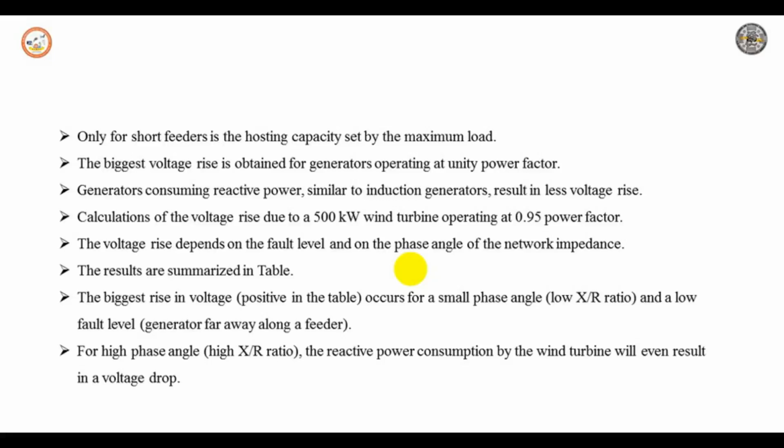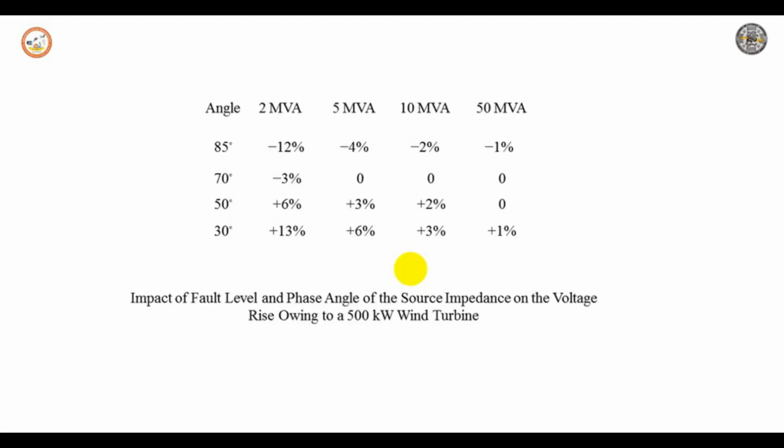The hosting capacity here is strongly dependent on the method used to prevent undervoltage. Using off-load tap changers for the distribution transformer will give a high voltage magnitude during low load for a location far out along the feeder. This seriously restricts the amount of generation that can be connected. The hosting capacity becomes smaller quickly when the generation is connected further along the feeder.